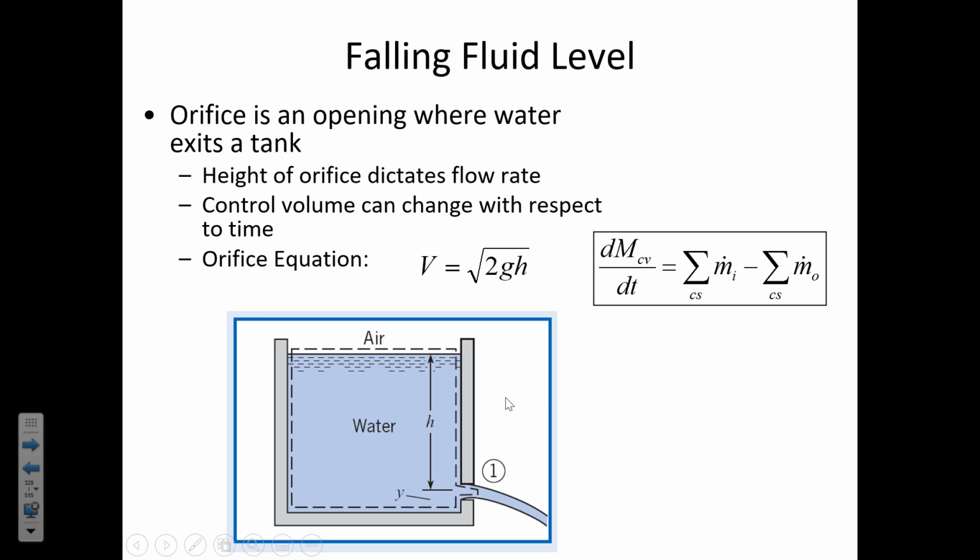Okay. In the lab, when we were using the orifice equation setup, we were testing the orifice equation, and we derived that from Bernoulli's equation, as you may recall, and got that the velocity of the water jet that comes out is the square root of 2gh. So that was derived by us looking at the energy at the surface of the reservoir and comparing it to the energy of the fluid jet that comes out. And of course, this velocity equals square root of 2gh.